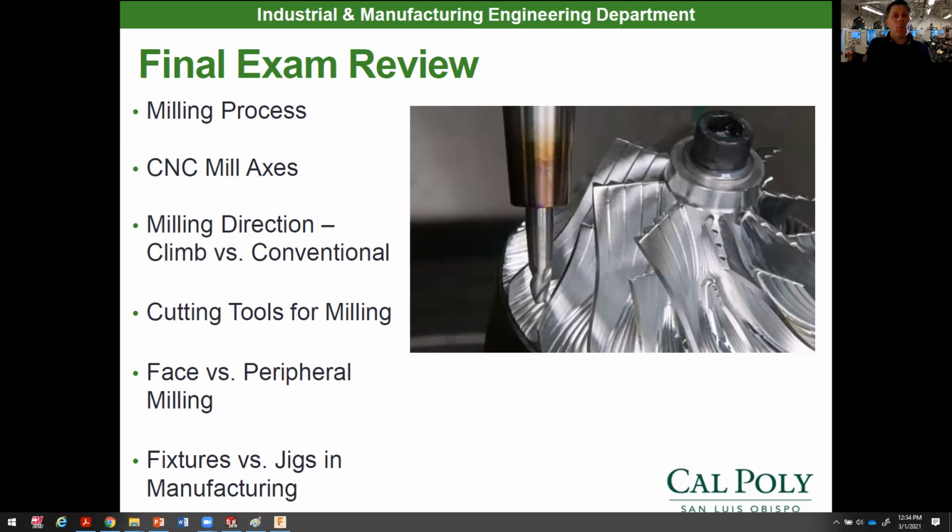And that's all based off the right-hand rule that we use for all of our engineering science classes, right? So know how the X, Y, and Z axes are oriented, maybe know which one the tool is oriented with, like the Z axis and so forth. Now, once we have those axes standardized throughout the world, we can start spinning our tool that we calculated the speed for.